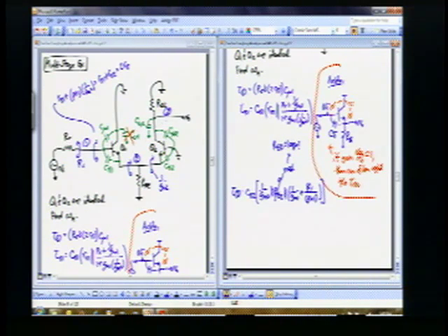They're both going to contribute a time constant that I can call the time constant at node 3. C mu 2 plus CCS2 times whatever the driving point resistance is at that node, which is simply RC2. It's RC2 times a 2R0 as well if you want to be complete about it, but we can neglect that 2R0.